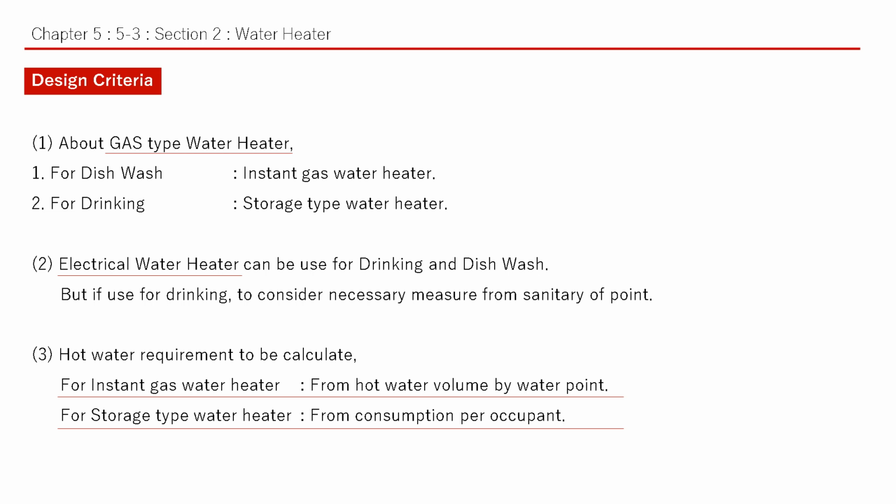3. Hot water requirement is to be calculated, for an instant gas water heater, from hot water volume by water point. For a storage type water heater, from consumption per occupant. For selection, whether instantaneous or continuous water flow is required, the design inputs required will vary depending on the equipment being selected.